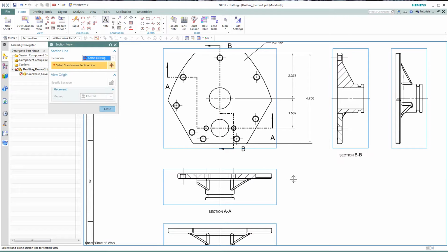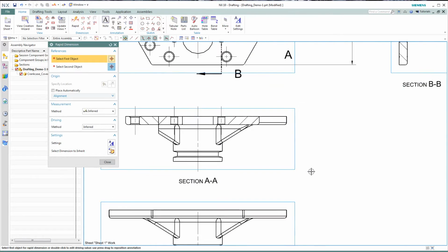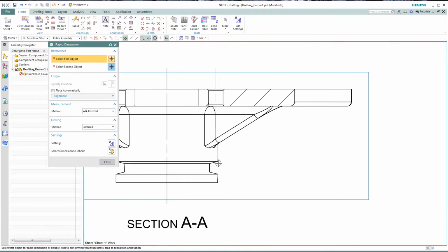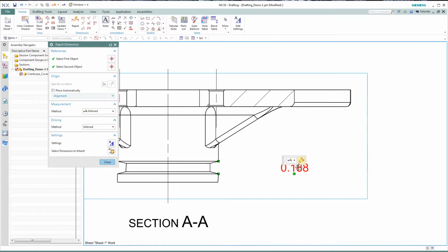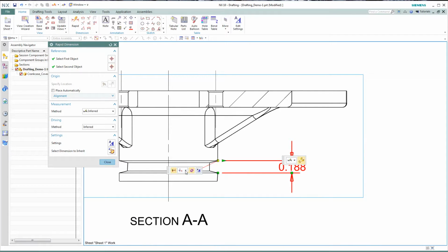Now that is done, we want to go ahead and add more dimensions, to show some new functionality that will be able to create a joggle. When we have a dimension that is kind of tight, we want to be able to create some joggle. In this case, we want to go ahead and edit that dimension. Make sure everything is synchronized on both sides.